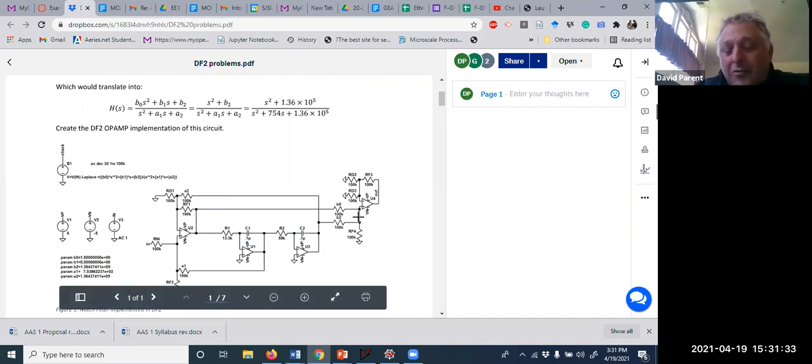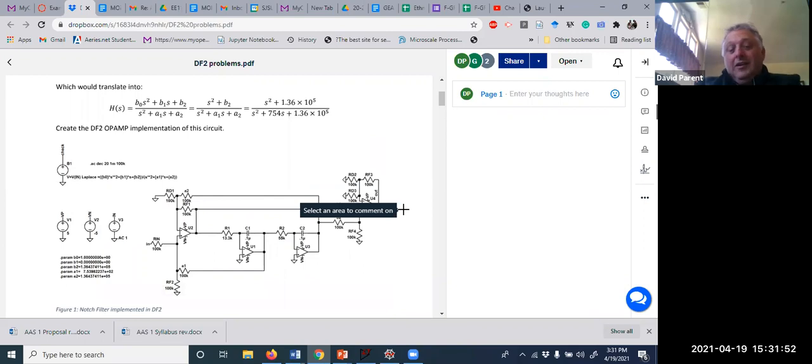There won't be any current flow. If all of these are tied to ground, they're not necessary because with no current flow, there's no voltage drop, and so this would be tied to ground anyway. By the time you're done deleting everything, you're left with an inverting gain stage, or an inverting gain stage that adds 0 plus the signal you want.